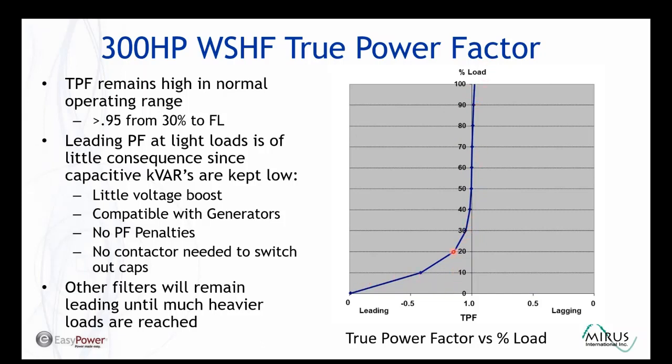Under light loads, power factor does go leading, but as mentioned earlier, we ensure that our capacitive reactance is very low, so that leading power factor is not going to cause problems with the power system when it's running at these light loaded conditions. So we don't require contactors to switch out the caps as many other filters would require.